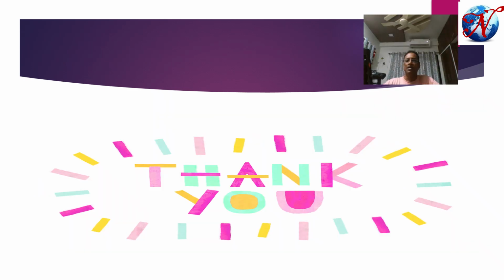Thank you for listening to this part B. In the continuation of ultrasonic testing in part C, we will discuss the initial calibration process and how we will standardize the equipment and the probe with respect to the code requirements of ASME Section 5 Article 4, and then how the reference block is prepared, what types of reflectors we are using, and from that particular block how you will draw the reference line, DAC or DGS.